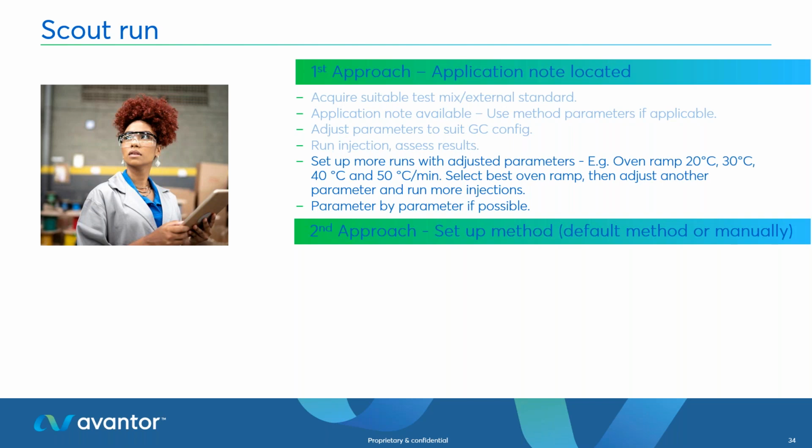If you're seeing any major issues, start to change a few parameters one by one, and then do another run, and then just keep doing this. And then if you're still seeing serious issues, then you can go back and just check if there's any issues with the GC.